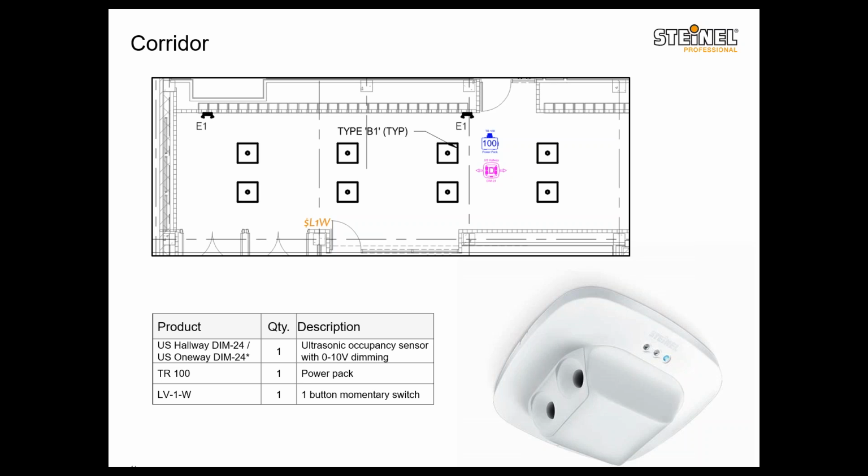Like the fixtures in my office, I think they don't dim below 25%. So I can set them in the app to 10%, but the fixture won't go below its design settings. In the app you can go to 10%, and if you have a fixture that can do that, obviously you can get 10%. If not, your lights will go to the minimum design of the fixture if you set the sensor to 10%.